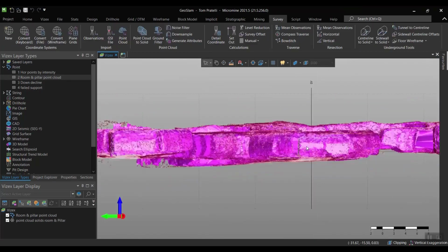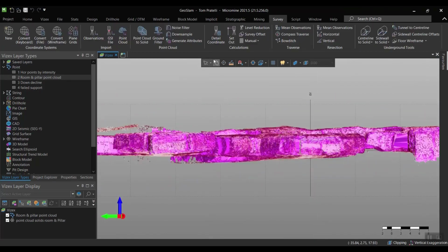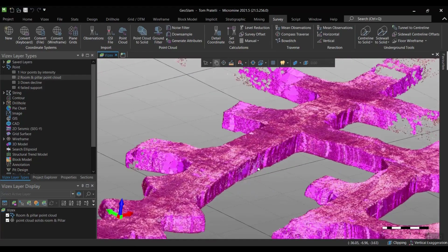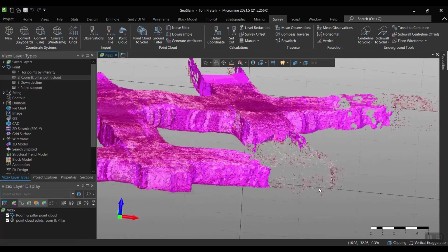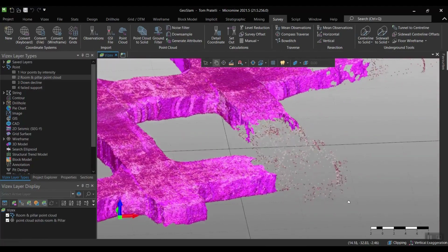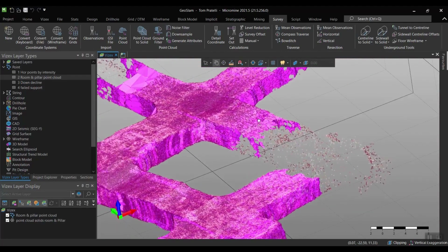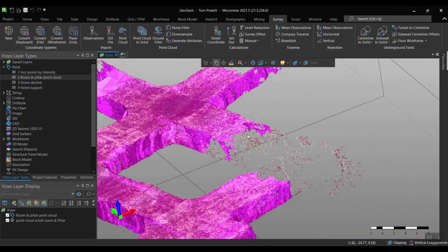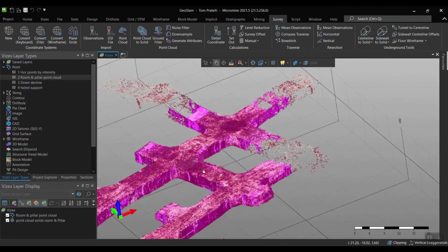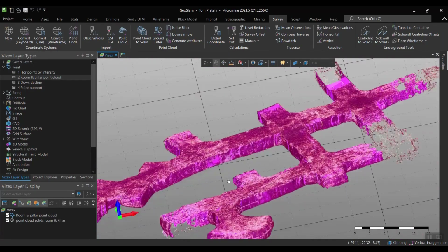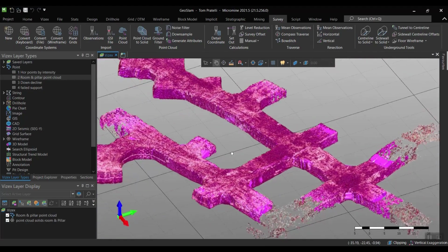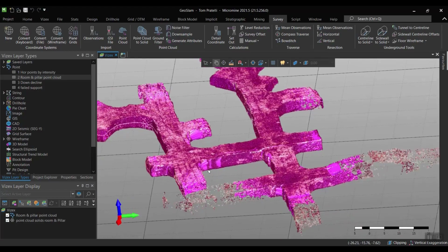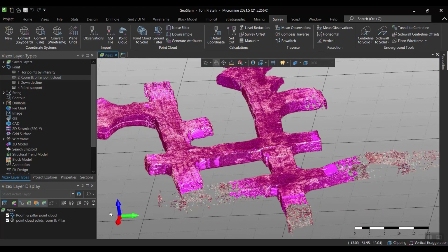And overall, that's a very well created surface that is actually a volume. You can see in particular areas just towards the edges where we maybe have come out of the scanned area, we can increase the webbing to make sure that's covered up if we wanted to, or we could include that in another scan and merge the two. So overall, a very good result and very quick and easy to create surfaces and solids from a point cloud.